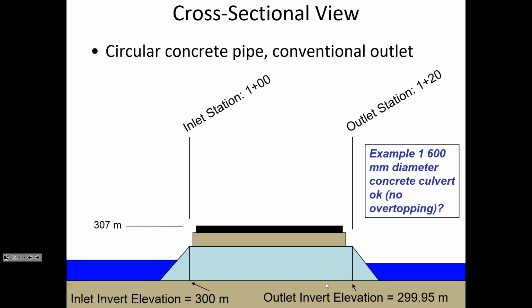Here's an elevation difference. And so the program is going to calculate the slope of the pipe from that. Also, we're going to assume that the elevation of the stream after the culvert matches up. Remember those pictures from the culverts in Colorado where the pipe was above the bottom of the stream downstream?